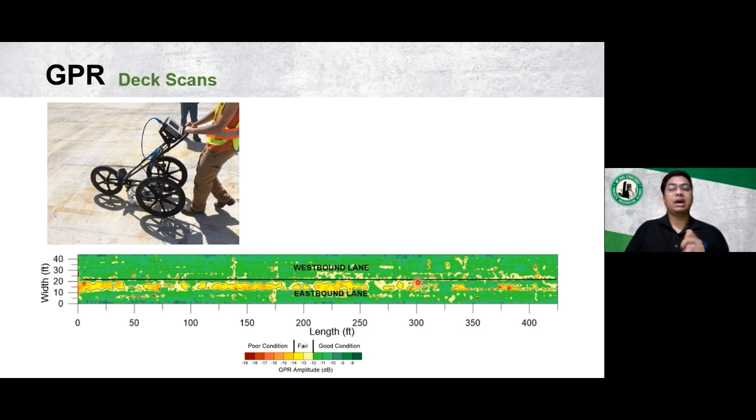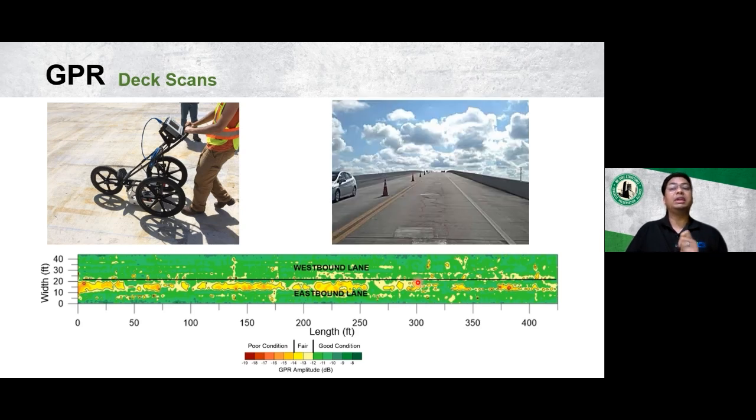The areas identified by the amplitude analysis closely overlap the delaminated and the spalled areas identified by the hammer sounding and dragging. So this serves as a double confirmation. So you get some data from the GPR and you verify it with hammer sounding, and then you can be very sure that the delamination or the subsurface defects are present in the concrete.